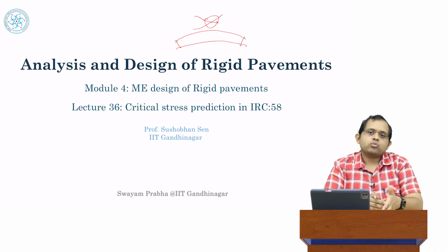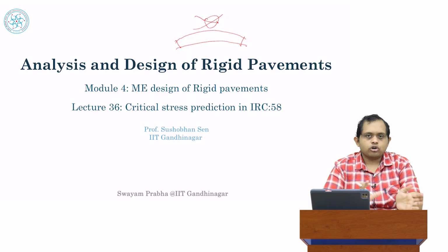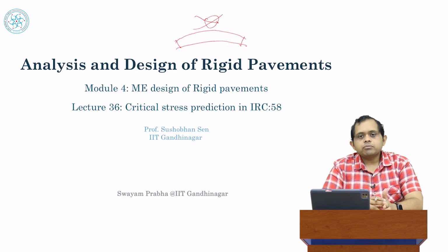But in practice, what we use in modern theory or modern design practices, in most parts of the world, is the finite element method. The finite element method is a numerical method. Without going into all of the details, I just want to remind you that in the finite element method, we take a differential equation, partial or ordinary, and we turn it, using a variety of techniques, into a series, a very large number of linear equations.